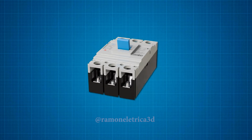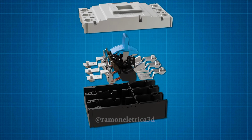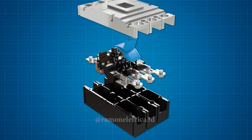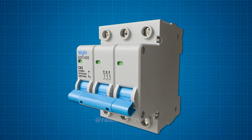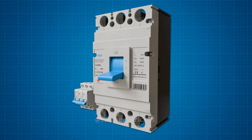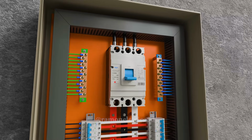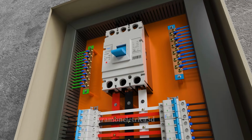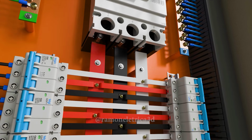It's also important to mention that you may need an MCCB even when the rated current is below 125 amps, even though MCBs with the same current rating exist. For example, there is a three-phase 100 ampere MCB, and there is also a three-phase 100 ampere MCCB. However, if the short circuit current at that distribution panel exceeds 10 kiloamperes, you must use an MCCB with a short circuit capacity above 10 kiloamperes.